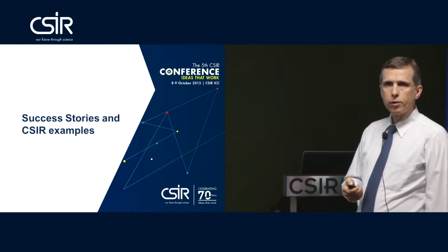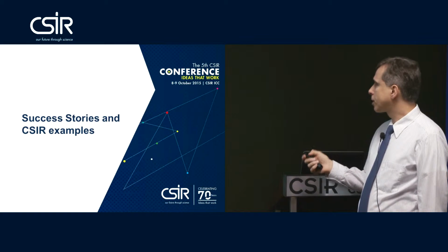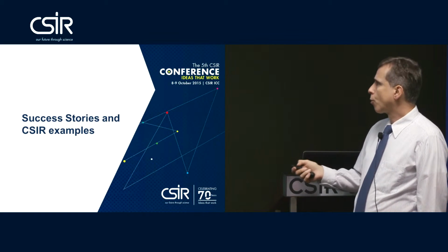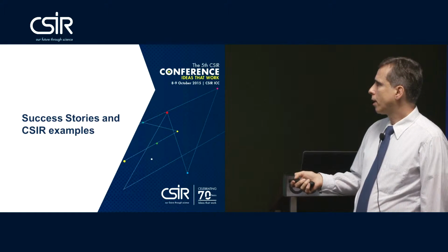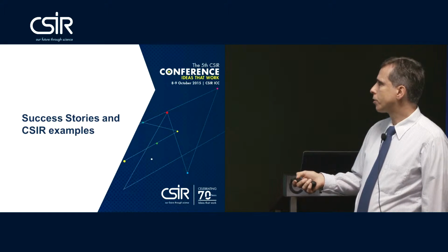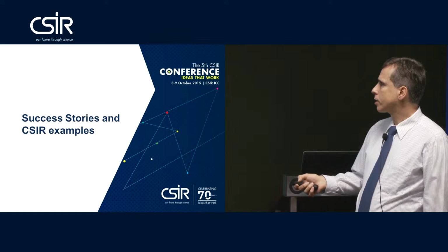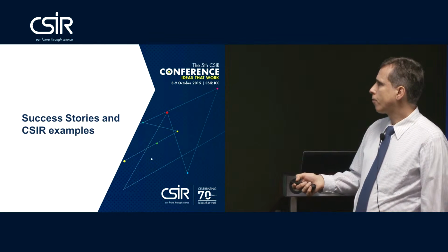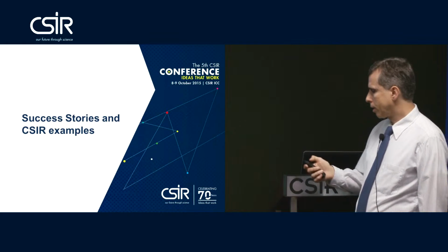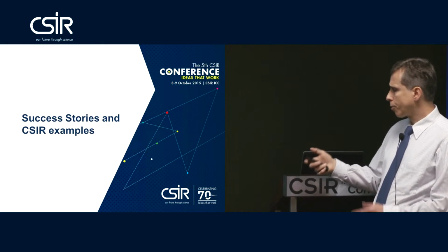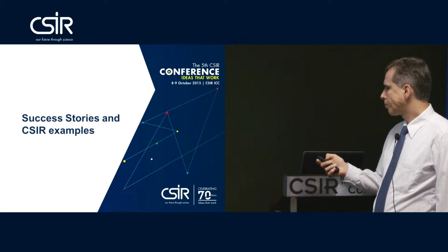And in particular, this is a scan matching method. If our robot sits here at point A in this environment, and let's say it's facing in the direction of this red arrow, and let's say it performs a 360-degree scan, and it finds in that scan these blue walls. Of course, it can't see around corners, so there's some limit to where it can see. And so we get a partial representation of the environment.